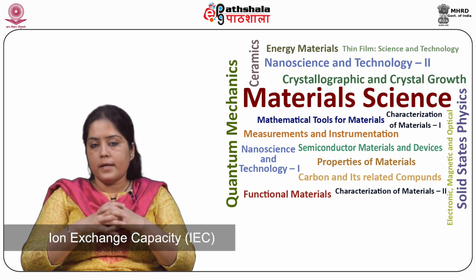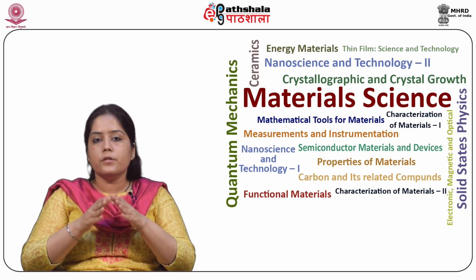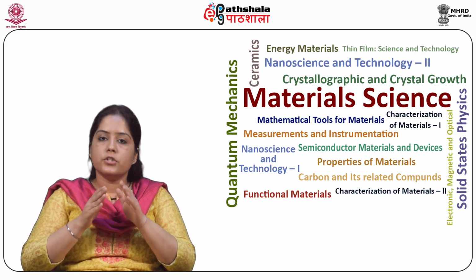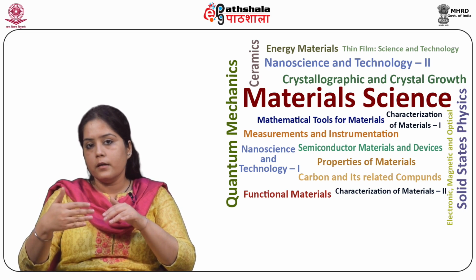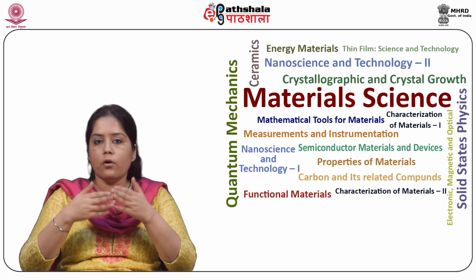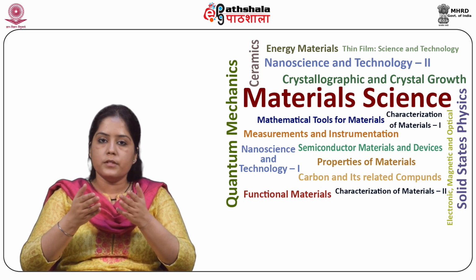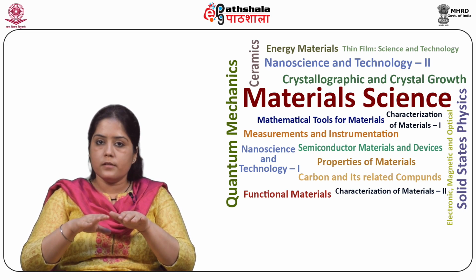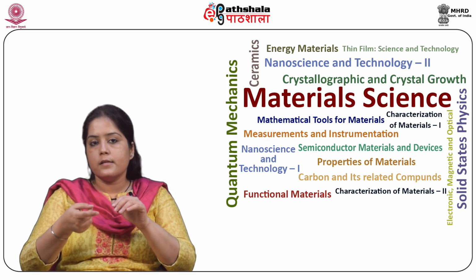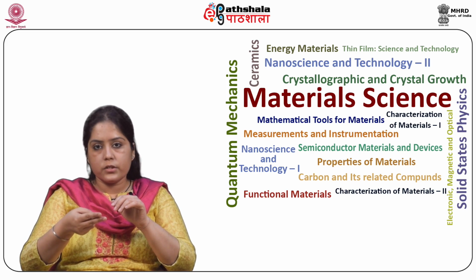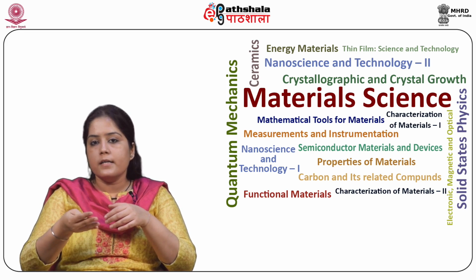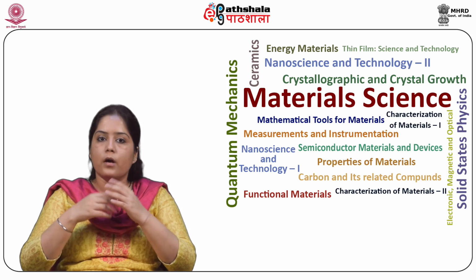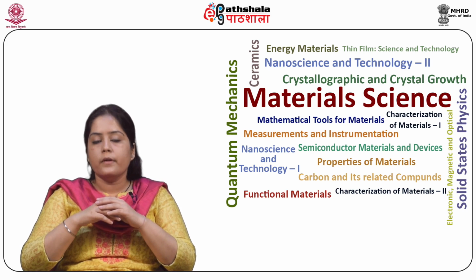Ion exchange capacity, or IEC, is often used to measure the charge carrying ions passing through the membrane, and the conductivity of the membrane is determined by various factors such as thickness, ionic group concentration, the degree of cross-linking, and the size and the valence of counter ions.